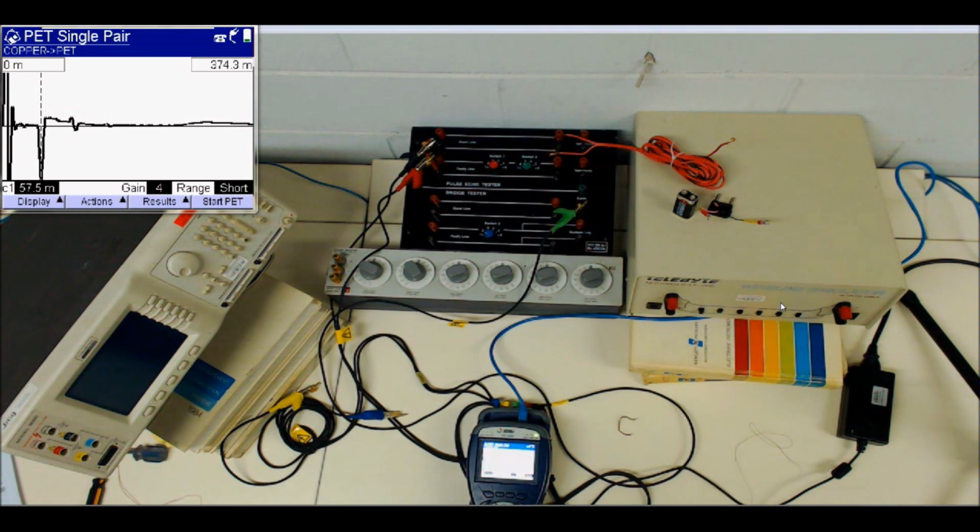If you look closely, we have a really sharp dip there, followed by an increase, a hill. That has to be a bridge tap. That is considered to be a bridge tap because, as we said before, a valley is a short, which is what a bridge tap essentially is, and then it's followed by an open, where the trace heads towards where our eyes went.